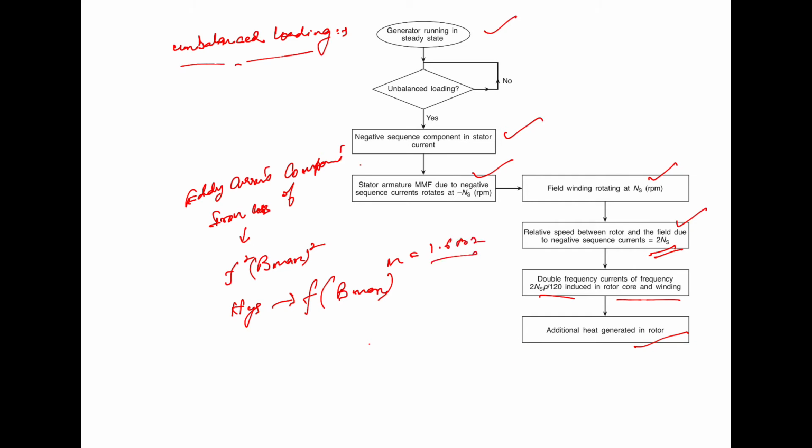Now, both the eddy current as well as hysteresis loss increase due to the double frequency induced currents in the rotor. So both of these will increase due to the double frequency currents.